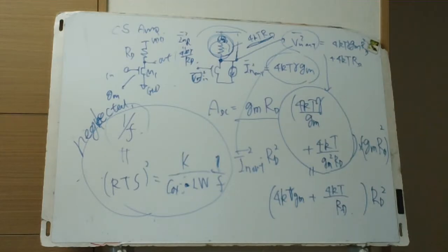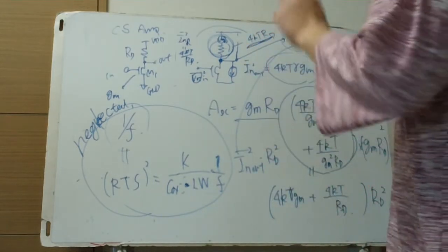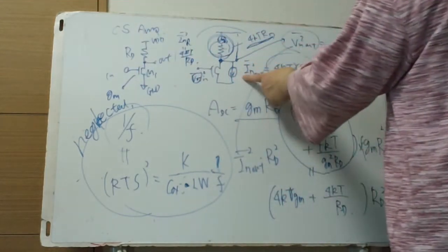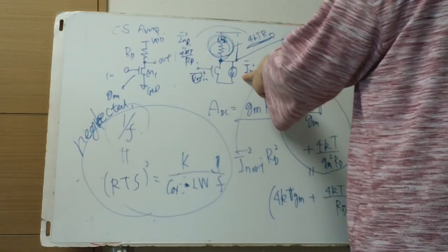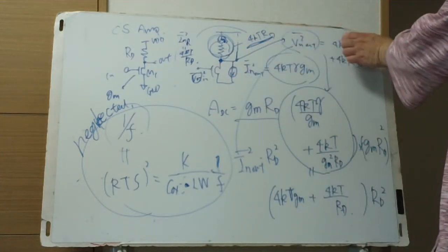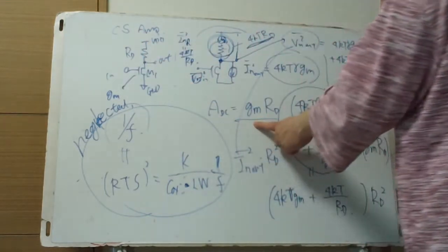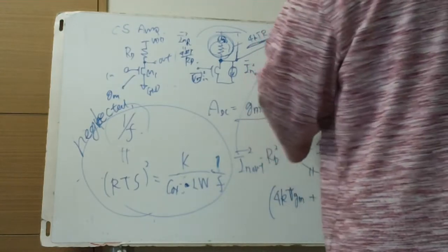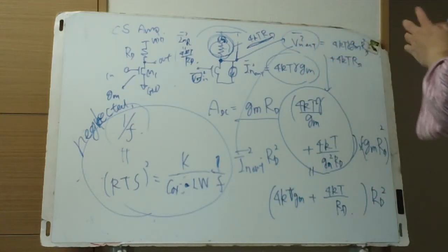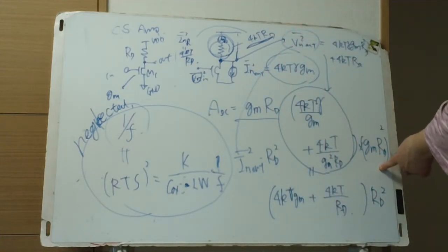What we did is the 4-step procedure. First, find each component's voltage noise and current noise, transferring current noise to voltage noise, and find the transfer function of this amplifier, gm RD, and adapt all the components, adding and multiplying by gm RD, getting V out.